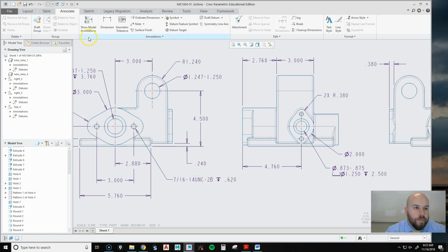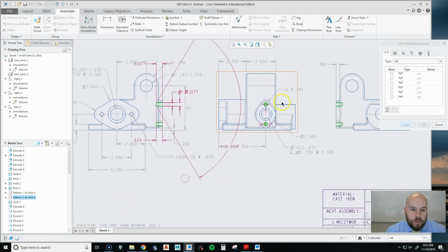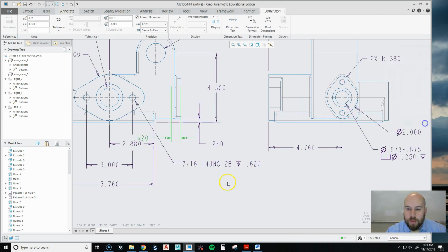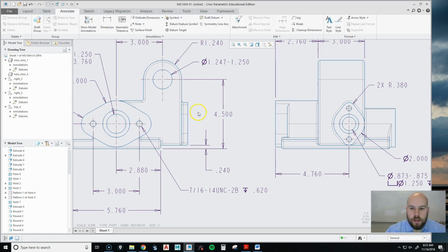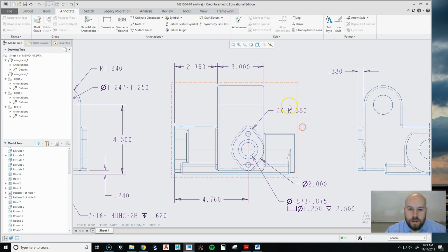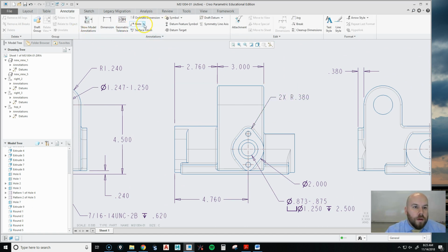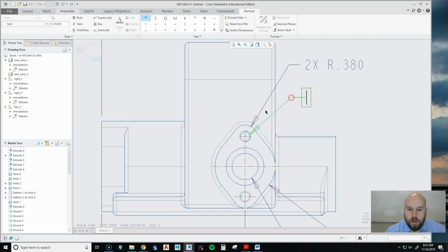That looks pretty good. So I'll go up here, move on to the next one. These holes, which are these over here, again, I'm going to need this depth. But these are threads, so I'm going to put a note in again. So this one is D77. I'll just delete that and remember that. D77. Move this one out of the way. Go to leader. Click here. Middle click. Notice I'm trying to get the arrow to point to the center.